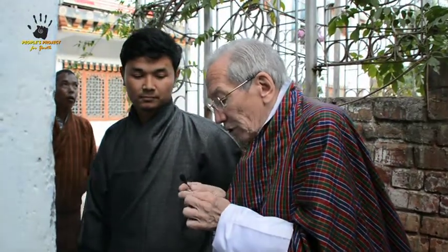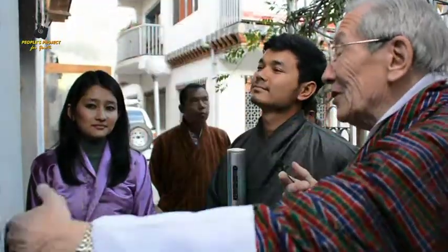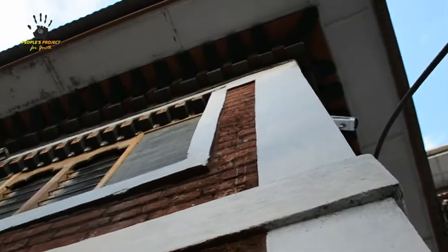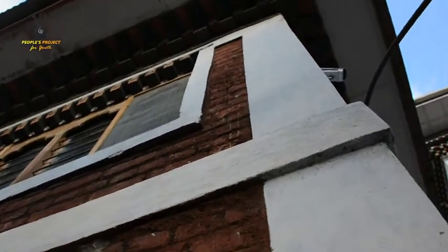If I were to take a square centimetre of this concrete, it would hold up a mass of 180 kilograms. So if I measured the area of this column, I could calculate quite easily how many kilograms this column could support. This is a very easy and quick way of seeing how much building this thing can hold up. If I wanted to build an additional floor on here, you could measure that and say whether this was strong enough to take the weight of an additional floor, also quickly, and you didn't have to knock the building down to test it.